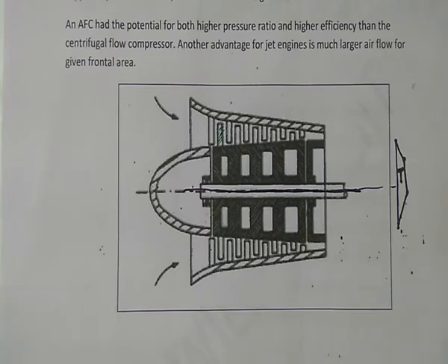There will be proper mixing of fuel and air, and you will get a high temperature rise, which is known as turbine inlet temperature. Then you'll have a turbine, which extracts some energy to drive major components like the compressor, turbofan and propeller blades. And then you have the nozzle, and then you'll produce thrust in the forward direction. So it's somewhat complicated. Let's go into bits and pieces.